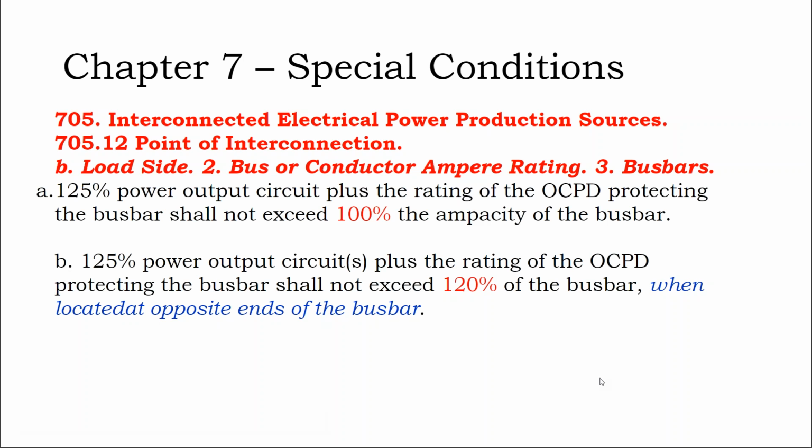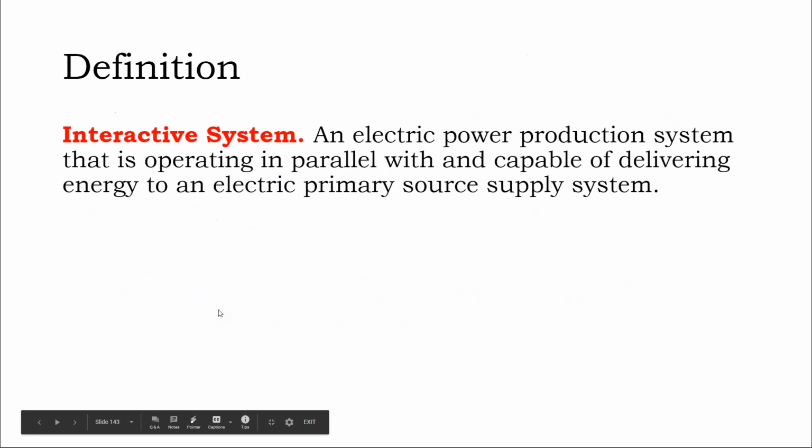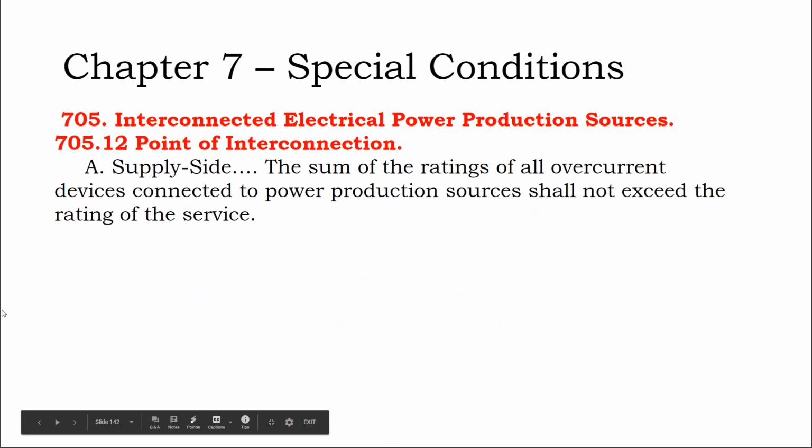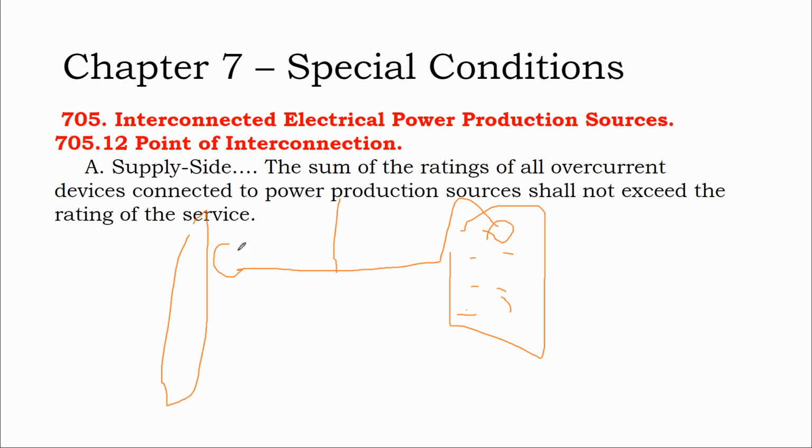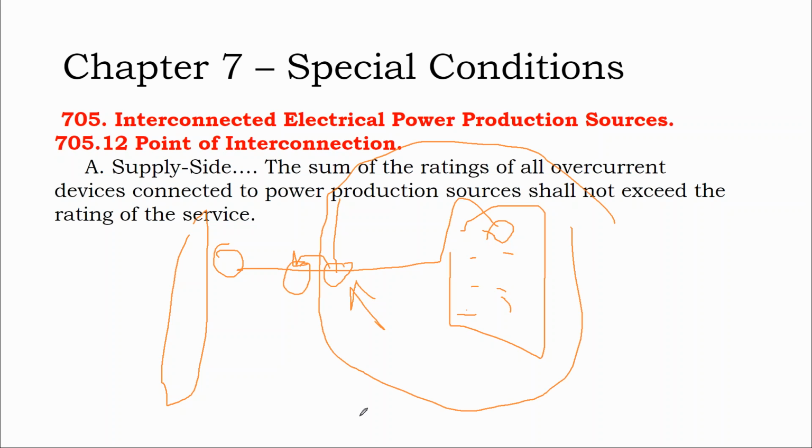If you're doing a supply side connection, you're putting in a larger system because that lower amount doesn't work. And so if you have your electric service panel here and you're intercepting these conductors between the grid and the solar array, you might want at this point to put in a 3-pole disconnect switch so that you can fully isolate the home.